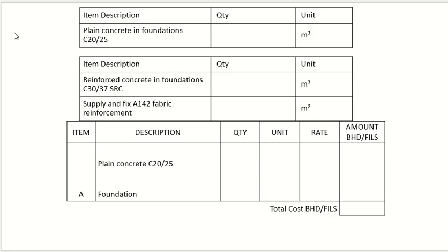But we are already calculating the reinforcement separately, right? So can I keep this row as it is in scenario 2? You can see the top two tables. Can I keep this row in the second scenario? The concrete description is different. You're not looking at the quantity only. So when I told you 100 BD per cubic meter, it was for plain C20/25 concrete. What concrete are we using in the second scenario?